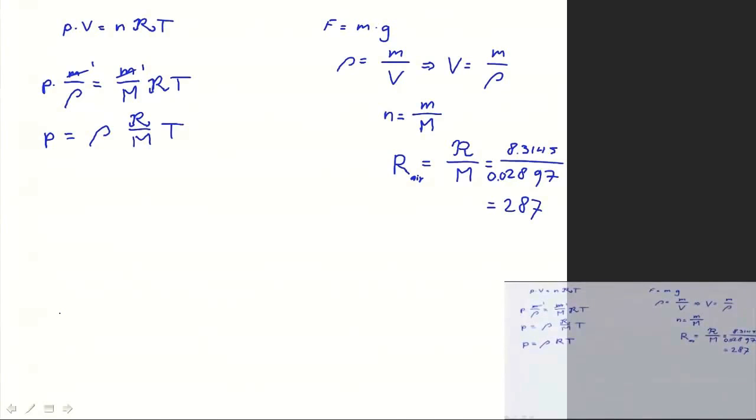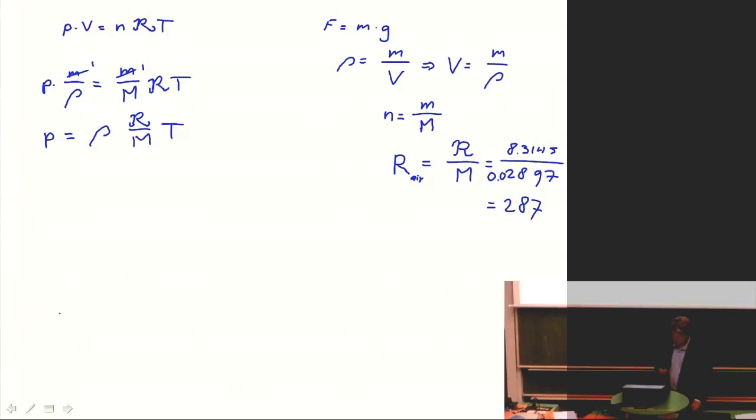It's not the general gas constant. R is for air only. If we compare different gases, if we're going to talk about balloons with helium, for instance, then we will need the formula one above that, with the curly R divided by the molar mass. So that's the new gas law that we use.